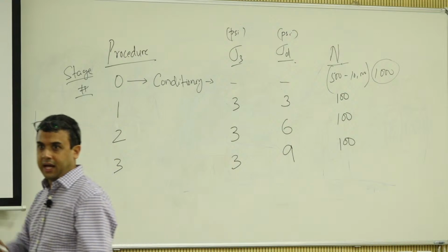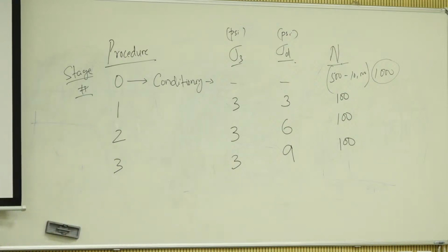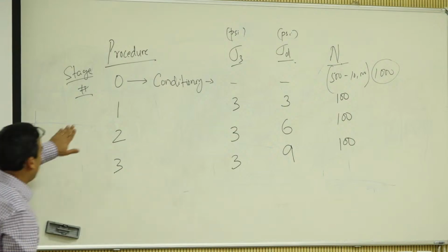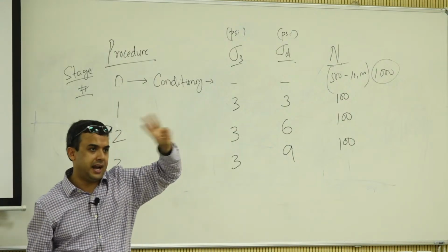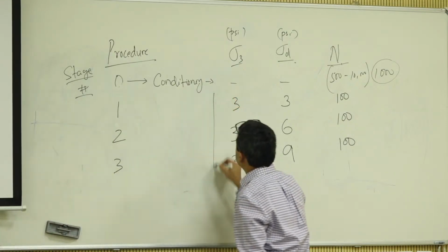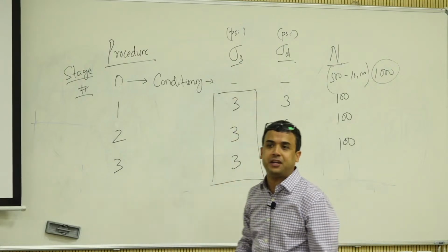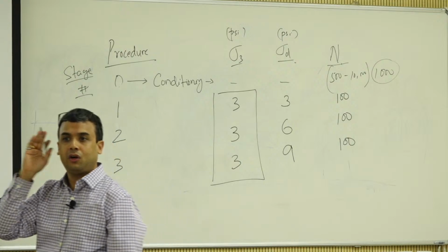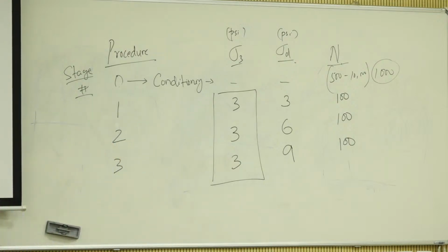Okay. After conditioning, how many sequences did we just talk about? 3. There are 15 such sequences. We'll look at the values, and in the tutorial today also we'll look into that. So after conditioning, don't worry about conditioning, the test has right now 3 sequences, and during the sequences, what did we do with the confining? Kept it constant, hence the test is called CCP, constant confining pressure.